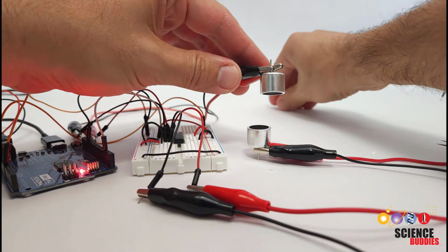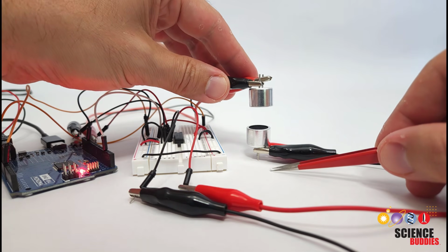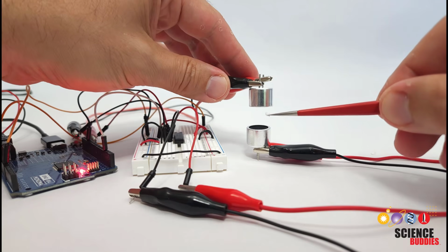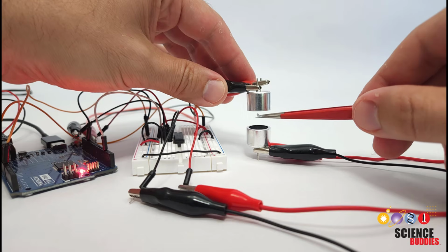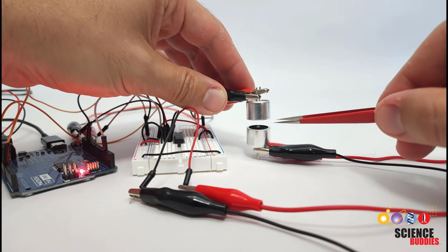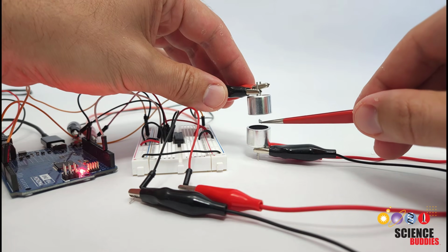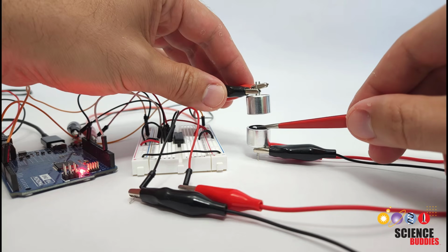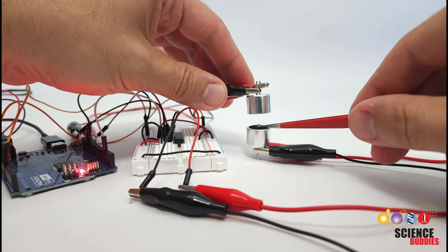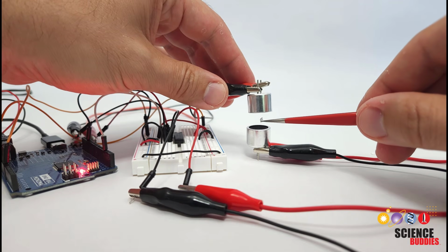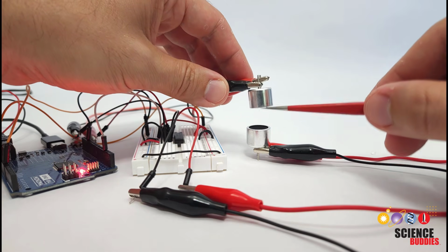So if I adjust my camera angle so we can see this a little better, I can now test this and hold my transmitters above and below each other, grab a little piece of foam with the tweezers, and see if I can let it go in there and get it to levitate. And we see that with 9 volts, it doesn't work particularly well. I was able to get this to levitate a minute ago, of course, before I was filming, but I'm not getting it to work consistently with 9 volts. The 9-volt battery I'm using is a little old, so I could try this with a fresh battery, but instead, I'm just going to go ahead and move up to a more powerful wall adapter power supply.